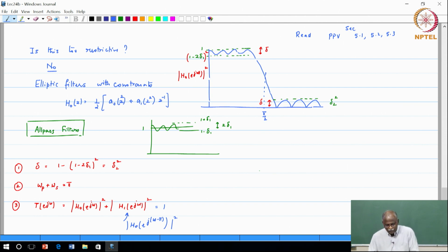So, the way we have constrained the design of the elliptic filter, this is something that was straightforward, something that can be imposed. The tricky part was how do you get the complementary property. Any pair of filters h0 and h1 that satisfy this kind of a property, that their magnitude squares add up to a constant, actually belong to a class of filters called the power symmetric pairs.